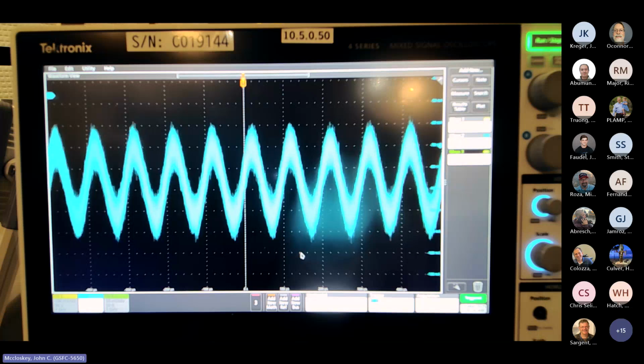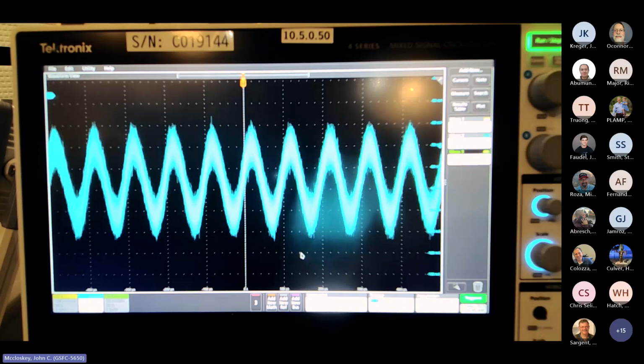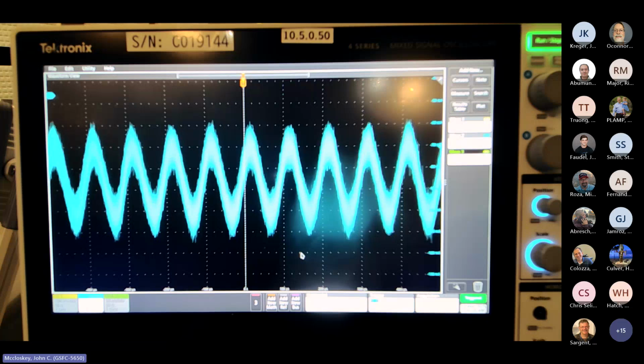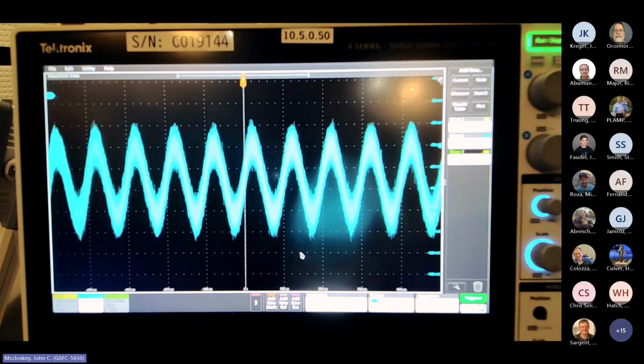I always tend to err on the side of a slight overtest. Between 9 milliamps and 12 milliamps, you're not going to break anything, right? I'd rather have a slight overtest at some frequencies than a slight undertest at others. That's just my preference. But anyway, that's our short circuit current at 10 kilohertz, 11.8 milliamps RMS. Remember that the voltage curve increased as a function of frequency until it leveled off a little bit above a megahertz.